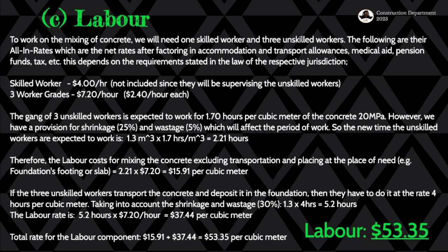Then taking into account the shrinkage and wastage 30%, we are then going to say there's need for more time again. We are keeping in mind that these are human beings that are working. They are not robots. So we need to extend time. If we increase the material, it means there's more work, which means they need more time. I hope that's sinking into your mind. So we need that 1.3 by the 4 hours to get the 5.2 hours per cubic meter.